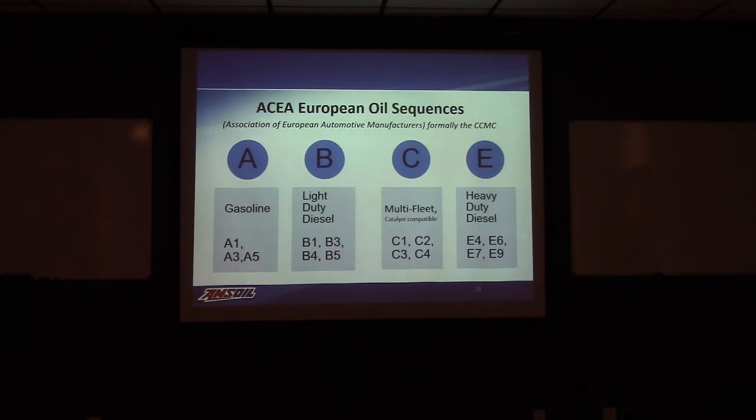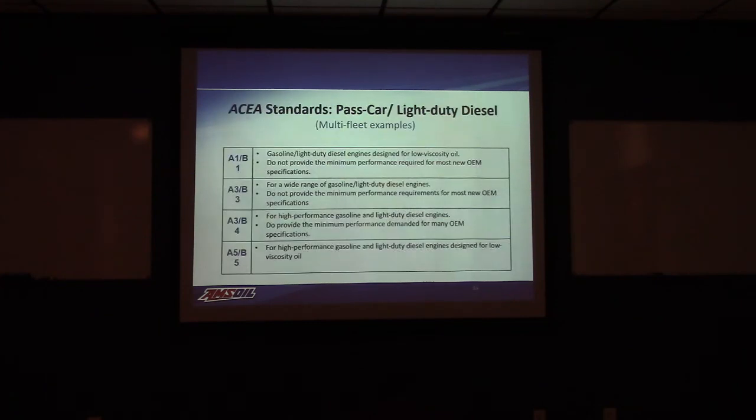It will talk about, in some cases, engine oil longevity. Some of these oils, when you get into the heavy duty diesels, for example E7s, E9s, tend to deal more specifically with extended life service oils for heavy duty application. It really divides it up much more specifically than the API does. Again, you can have multiple ratings, both gasoline and diesel, so in many cases they can be used in mixed fleet type applications.